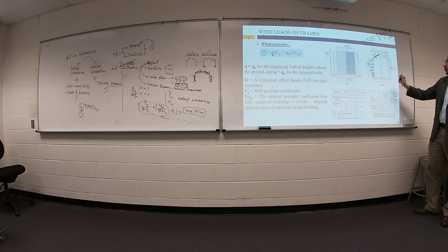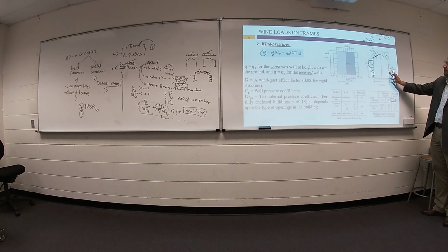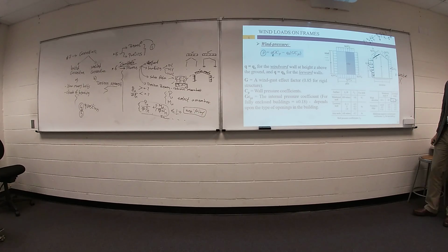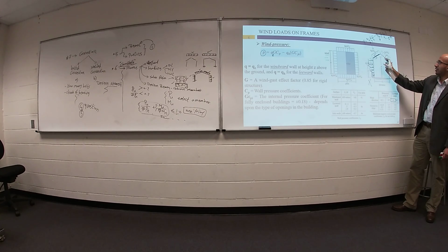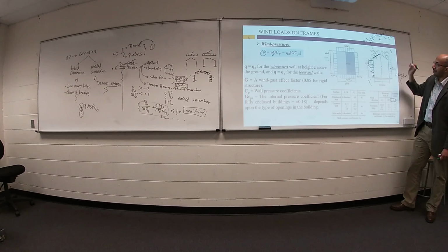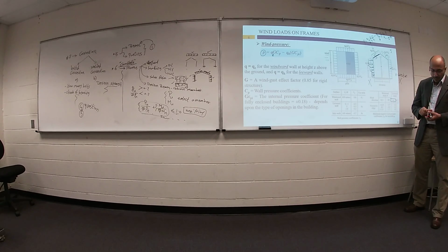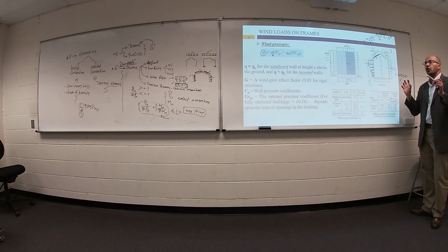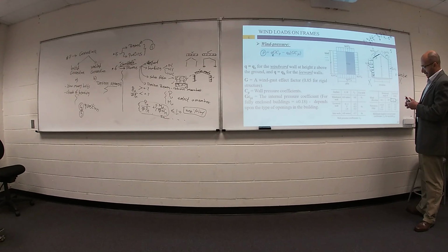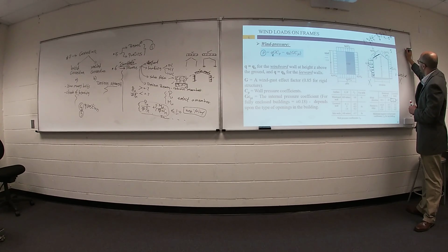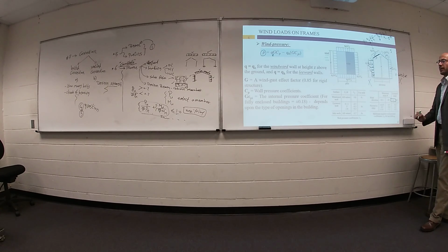Remember, for your wind load, for this member, it will be in X direction. So you can choose capital X. For this one, you can choose capital X. But for this one and this one, we are going to use small y. Small axis means local axis. Any inclined member, your local axis, x or small x, is in the same direction of your member.